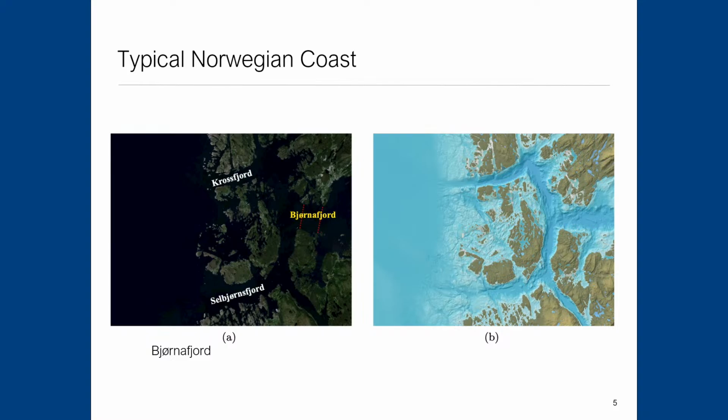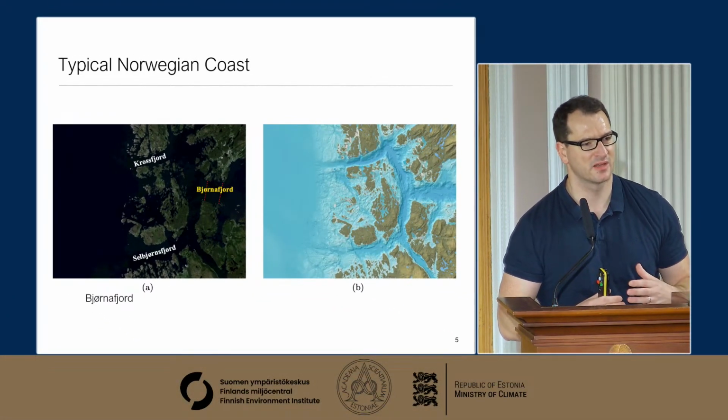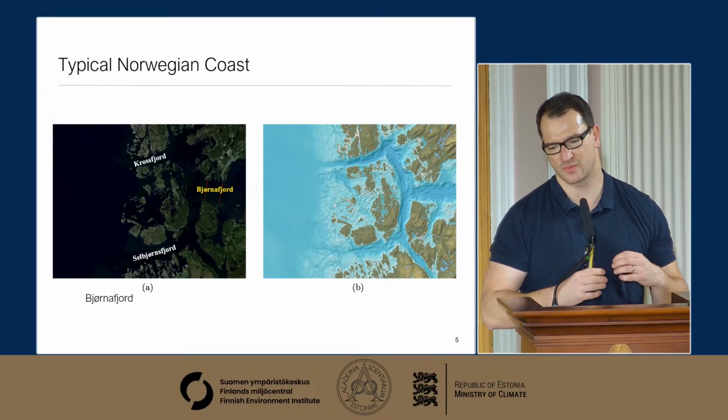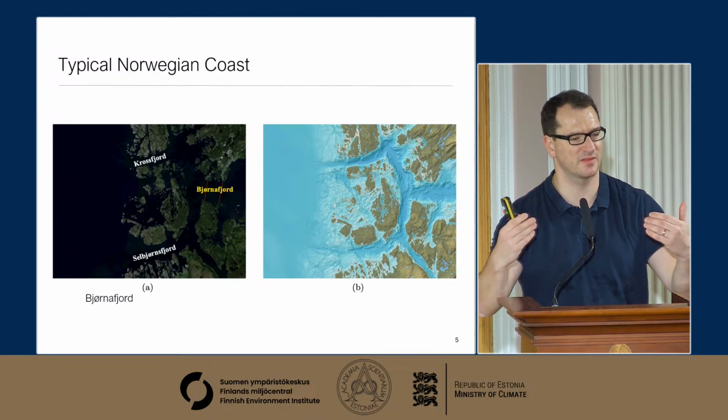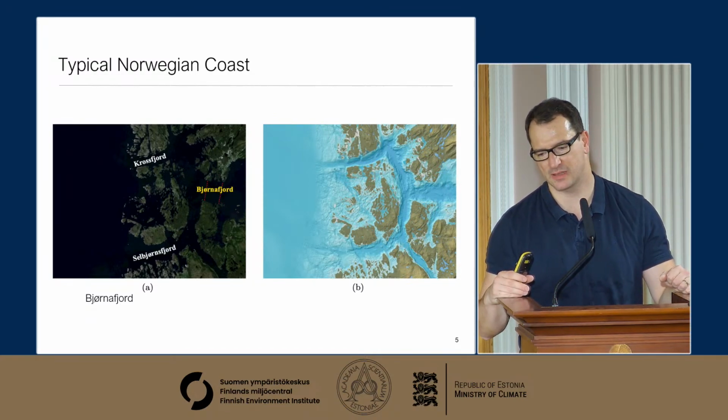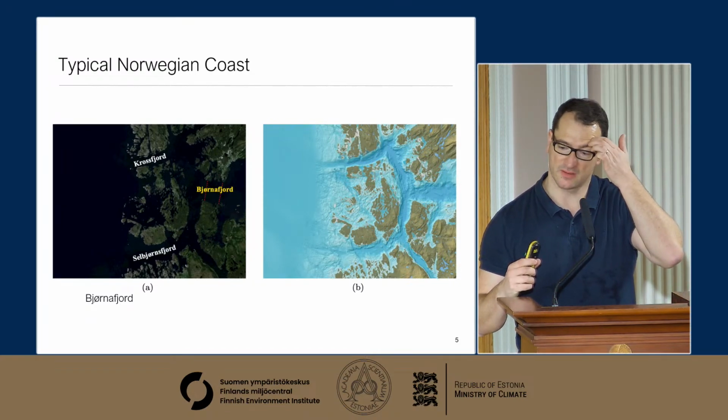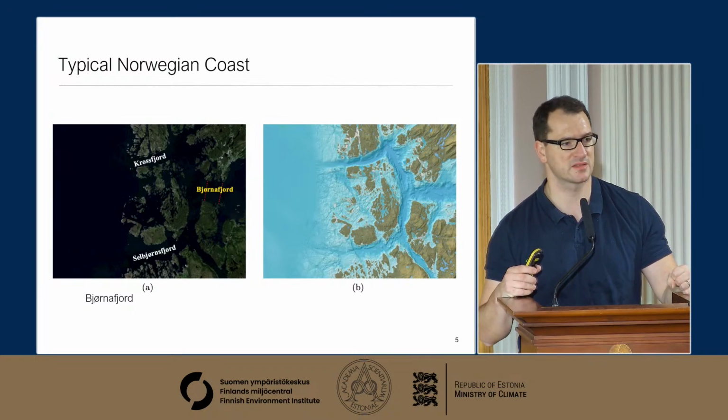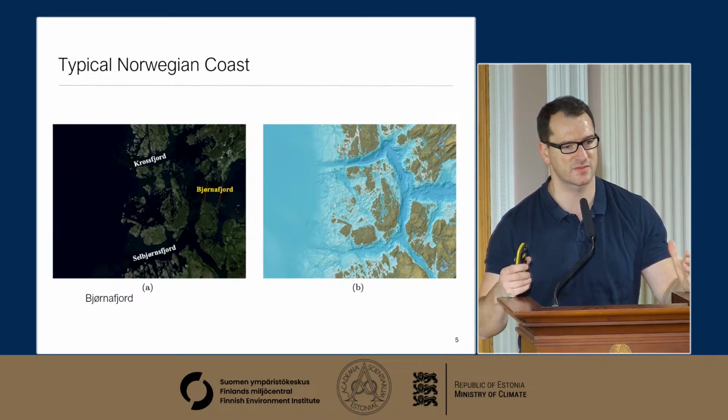And on the other hand, spectral wave models like SWAN, we have seen this yesterday, would struggle with the diffraction. So in the Norwegian coast, we have a lot of islands causing a lot of diffraction, and so the waves are not fully blocked, but just diffracted around the islands and continue to propagate. And this is why, for a coast like this, it's also very important to consider phase-resolved waves.